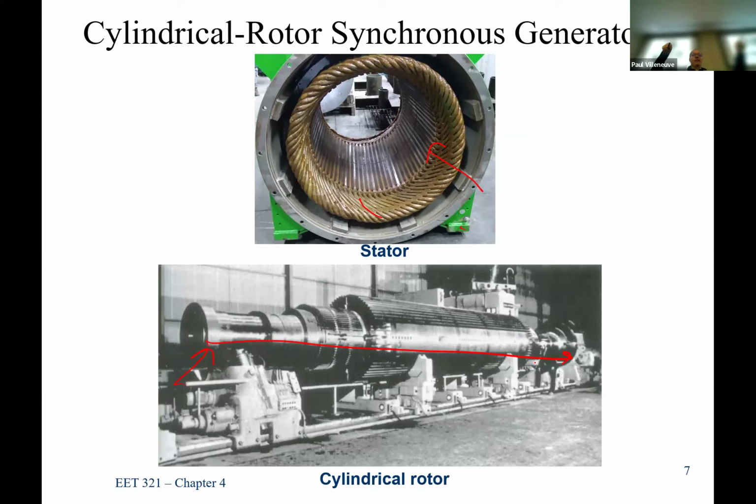So they actually have these things in big generators. It's called turning gear, and it just sits there and spins the unit at a really slow speed. The whole reason it rotates is to make sure that the turbine doesn't bow. If you've been shut down for a long period of time, you're going to have some bow in your turbine. So then you have to heat the unit up and slowly rotate it until there's no vibration and no bow in it.